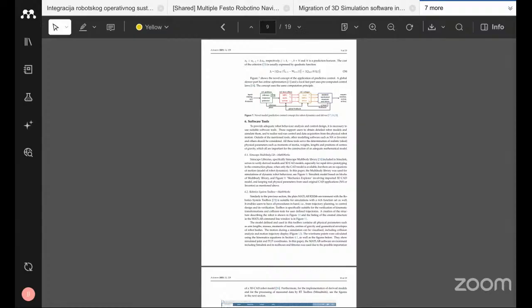Another one is Simscape Multibody from MathWorks, a multi-body modeling library. Using the CAD model, we can conduct the dynamic simulation. Import the CAD model in Simscape, define the mechanical joints, use the link masses and inertia, simulate the gravity effects, connect motors or actuators, visualize the joint motion, test and connect the controller, and verify the dynamic behavior.